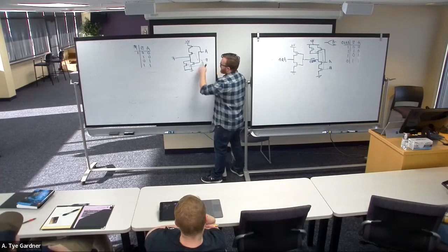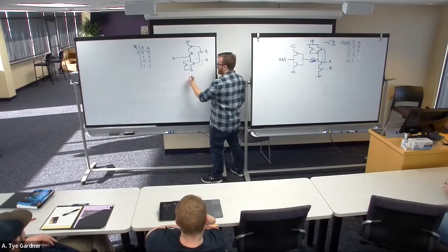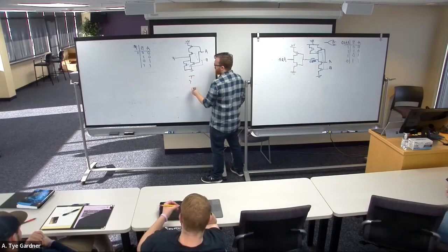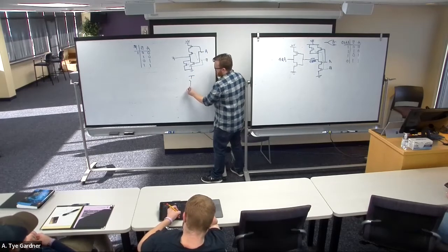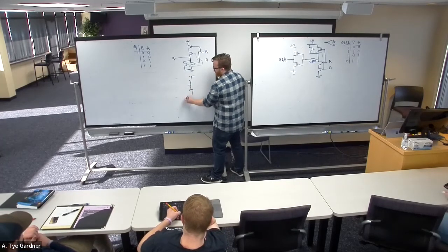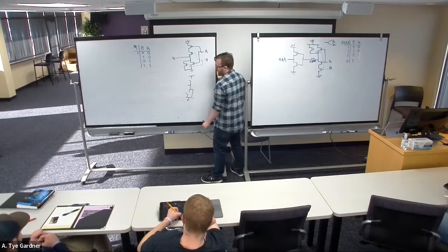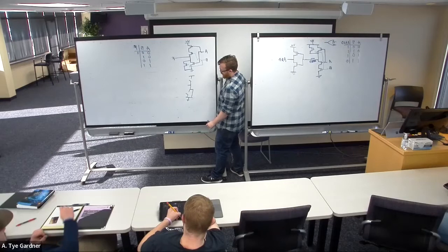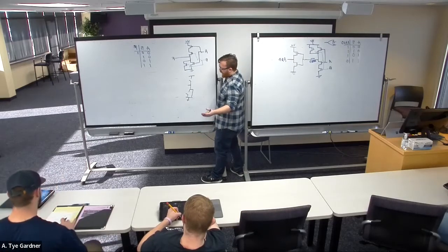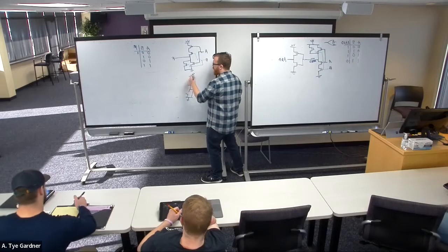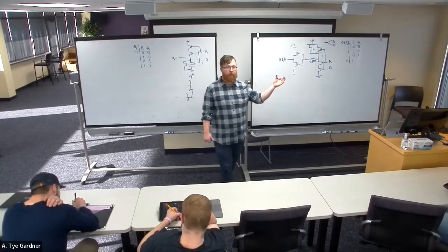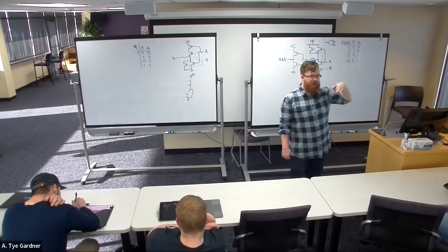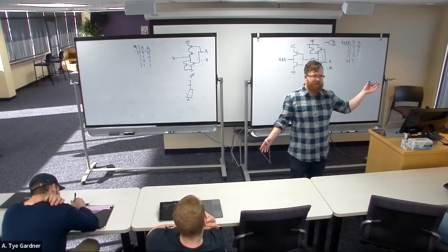Which is to say, well, I said A is my 1. So I have from power, I have a switch that's open. I have a switch that's closed. F comes out. I have a switch that's closed. A switch that's open. This is my circuit. Is there a path that I can take from VCC to ground? That would be a problem, right? Because if I connect power to ground and there is no resistance in between, what is my current?